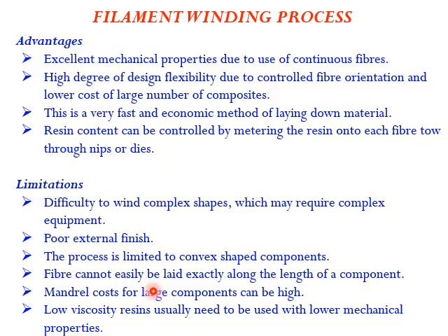Low viscosity resins usually need to be used, with lower mechanical property, because if you use a highly viscous resin, it will not stick to the fiber material and will just flow away. So to ensure that, low viscous materials are used.